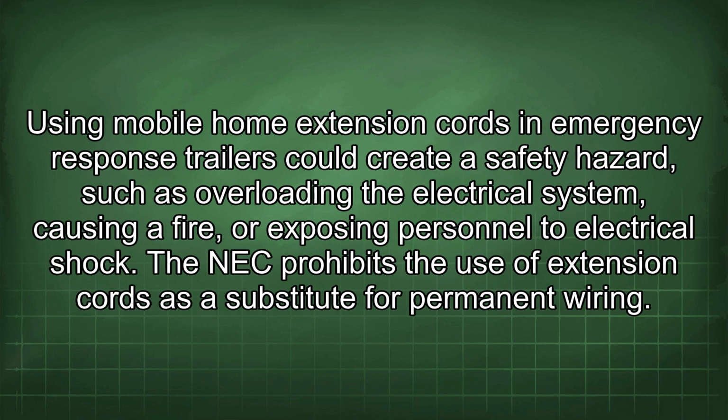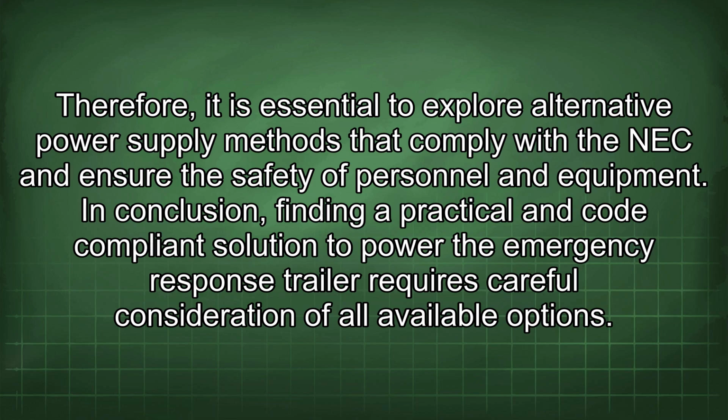Using mobile home extension cords in emergency response trailers could create a safety hazard, such as overloading the electrical system, causing a fire, or exposing personnel to electrical shock. The NEC prohibits the use of extension cords as a substitute for permanent wiring. Therefore, it is essential to explore alternative power supply methods that comply with the NEC and ensure the safety of personnel and equipment. In conclusion, finding a practical and code-compliant solution to power the emergency response trailer requires careful consideration